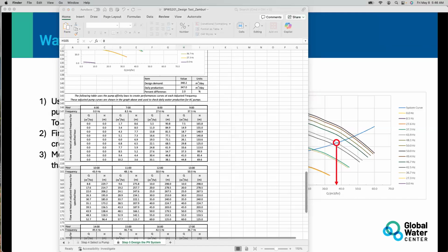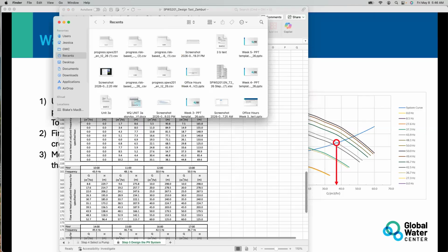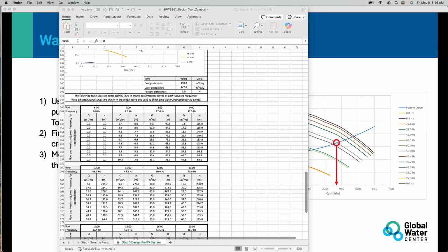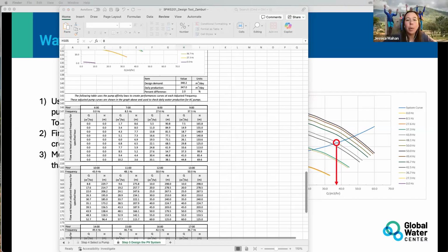And the adjusted values, that's only if you would go over the manufacturer specs. There's no other adjustment you need to make to those values. Correct. So in our example, our pump is 50 hertz. You might, depending on your location, have a 60 hertz pump, and then you would just make sure it doesn't go over 60. Exactly.